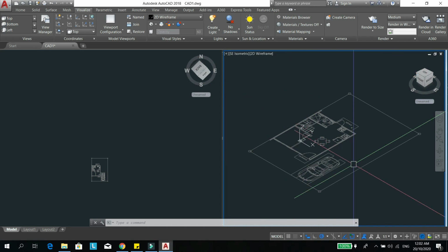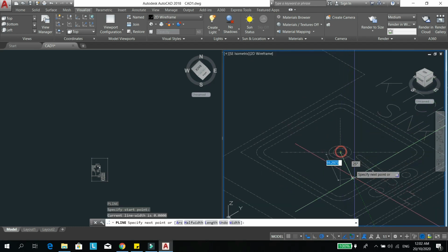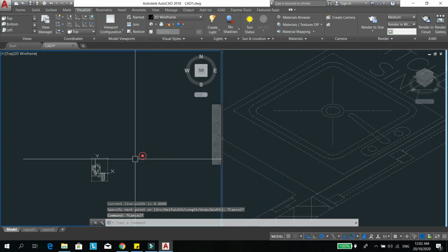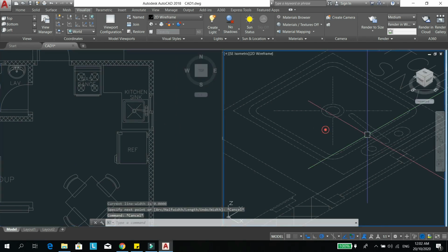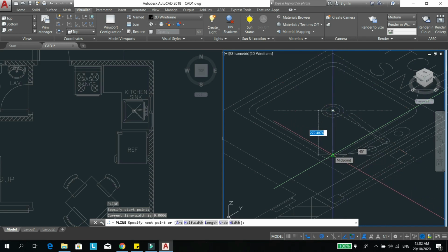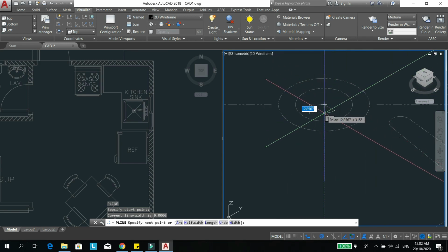Okay, ito nagbago din. So, para once na nag-create kayo ng lines, for example, soil pipe, makikita nyo kung it runs along z-axis, y-axis, or x. So, currently, wait lang, zoom in natin para makita. Okay. So, dito tayo, PL, press enter. Nakikita niyo nasa x and y axis pa rin tayo. So, dapat nasa z axis tayo. Okay.